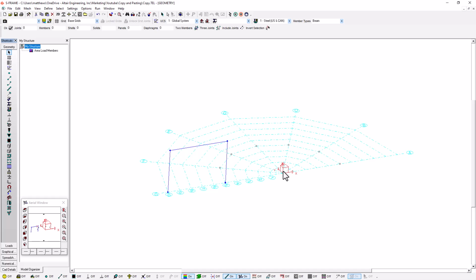And I can use the user coordinate system to place this coordinate system in different locations. But I'm going to press Control-C with the knowledge that this particular coordinate system is basically origined 5 meters away from the start of my column here in the X direction. So with that knowledge in mind, let's just press Control-C. Now this selected data has turned a maroon color to indicate that it's been selected.